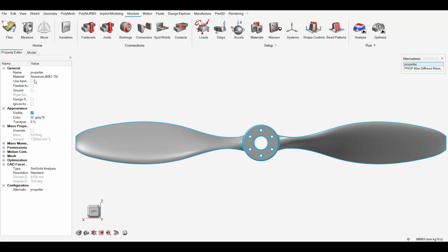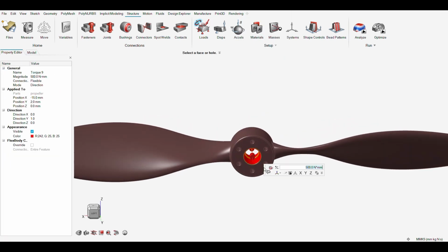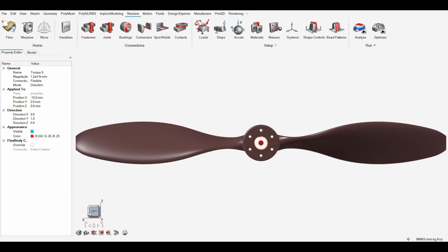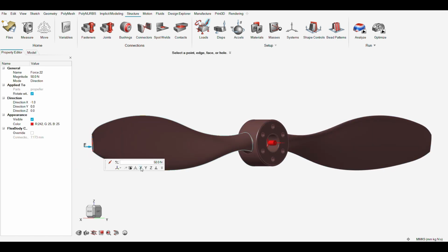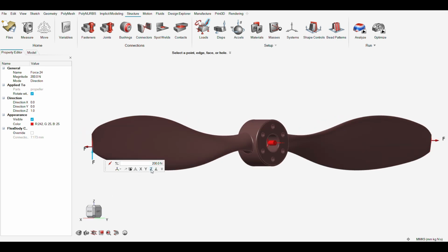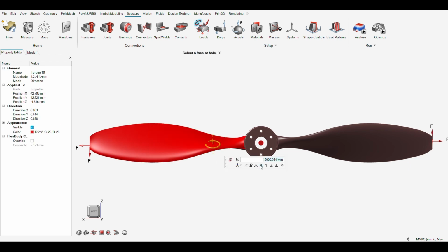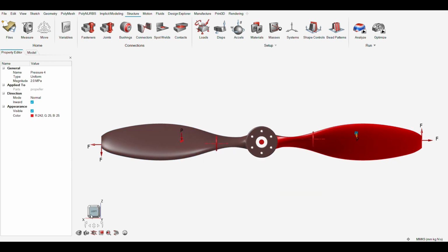To begin the optimization process, first, we define the design space. Now loads. Torque, 120,000 Nm. Aerodynamic forces, 200 N lift and 50 N drag. Centrifugal forces, radial forces peaking at 500 N. Hydrodynamic pressure, 2 N/m². We have applied the same loads and constraints from the structural analysis.